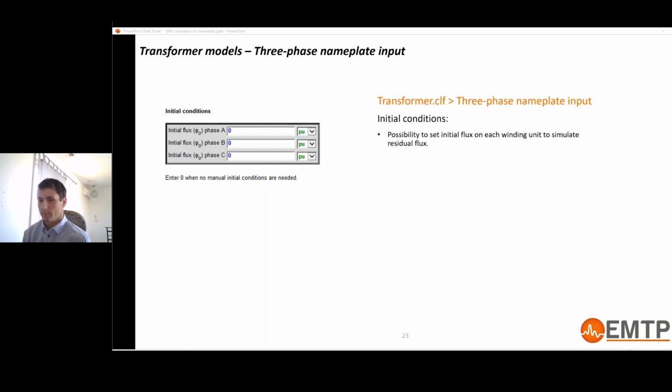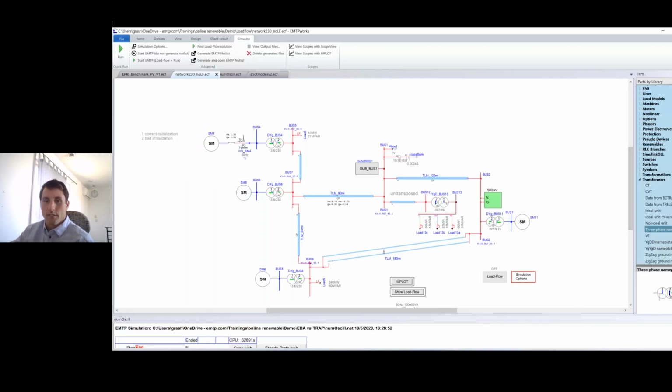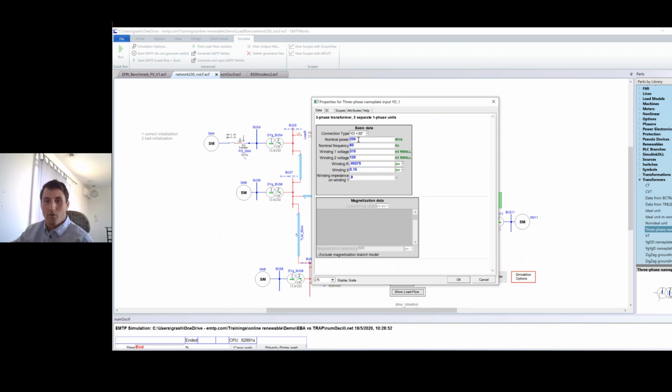It just says, is there an easy way to model tap changing on the transformer? Yes, there is a very easy way. The easiest way is to put in series here another transformer where you put 0 impedance, and you put your tap here. So you put 1 and 0.9 and 0.95. That's the easiest way.